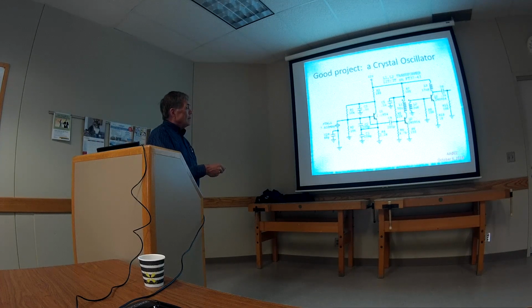But basically the Colpitts is this part of it, and it's driving some other stabilizing circuit and power amplifying circuit. So with a Colpitts Oscillator, the key thing to know, of course, is you always recognize it with the split capacitors here, right? Hooked from the base, and then hooked to the emitter. And then the crystal is hooked out in here somewhere. Now this 68P obviously is not being used right now. It's shorted up, but if you want to pull a crystal a little bit, you can hook up a capacitor here instead of this short. Right now it's shorted out, but that's where the crystal hooks on, and there's your basic Colpitts Oscillator in a pretty fancy circuit. It's really a nice one to build.